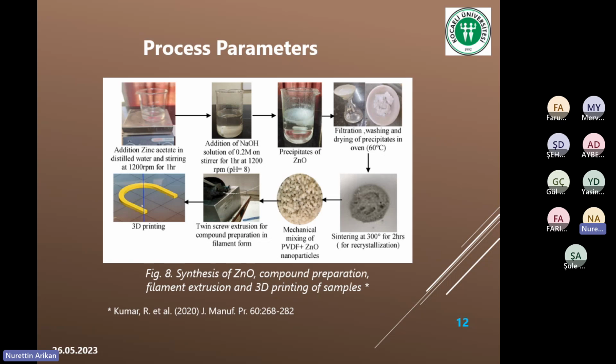However, it's quite risky because the piezo ceramic or ceramic dopant particles are very abrasive, and they will probably wear out the nozzles after not excessive, but even short-term printing of these composite materials.